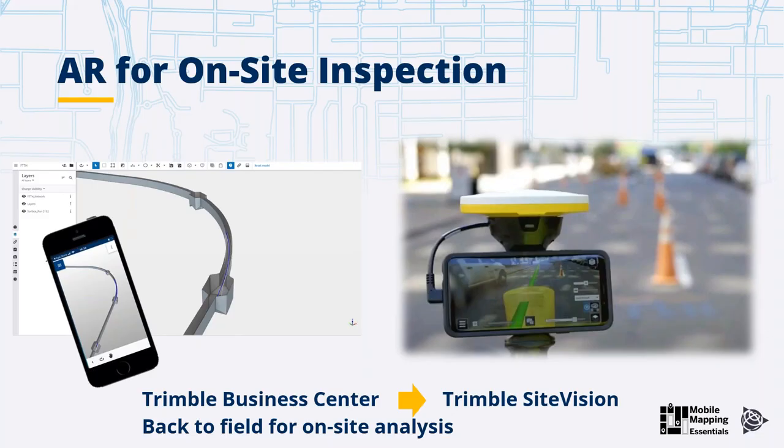And once this model is on the SiteVision, the operator has the chance to do measurement, mesh against reality, or maybe mesh against GNSS position, because the SiteVision kit is also equipped with a GNSS antenna, so you can also make RTK GNSS measurements. And so from this point of view, the SiteVision can be the final step, the last mile, if you like, element of the workflow where you can really see how your project will look like in the field, right?